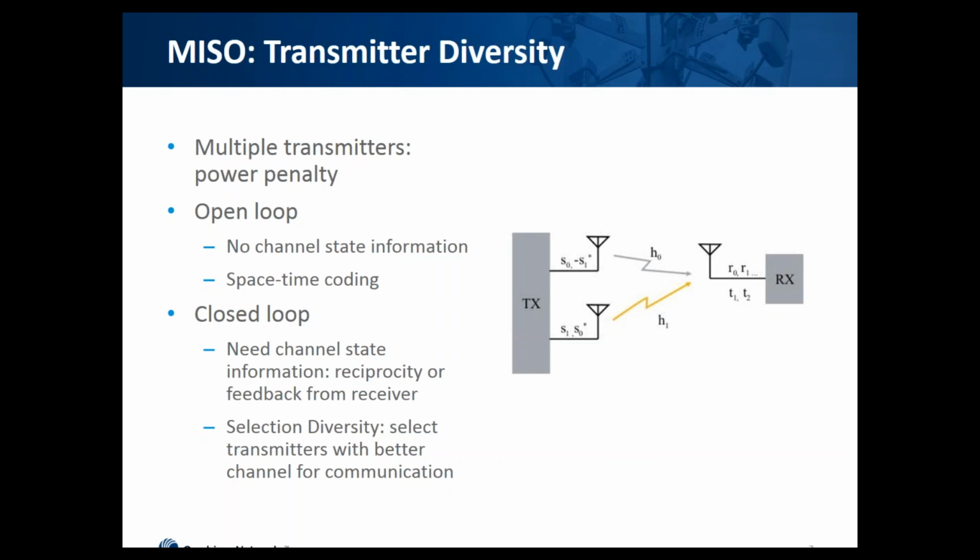The second consideration is that we don't want to send the exact same signal from all antennas. If we do, what happens? This is the same case of constructive and destructive interference we just discussed. If the signals are the same, but traveling through the two channels, they arrive with opposite phases, they could cancel out. This, of course, is not desirable, as you were better off without the second transmitter. So we know we cannot send the same signal. Then what can we send?